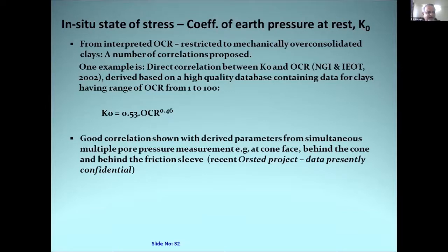Recently, Ørsted, previously Dong Energy, had a project. Unfortunately, the data is presently confidential. I was to some extent involved with that project, and we found that good correlation is shown with derived parameters from simultaneous multiple pore pressure measurements, like cone face, behind the cone, and behind the friction sleeve.